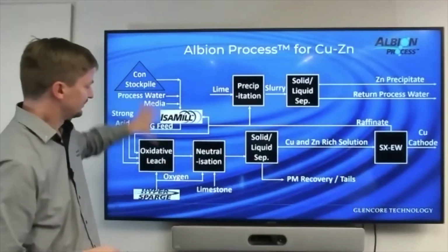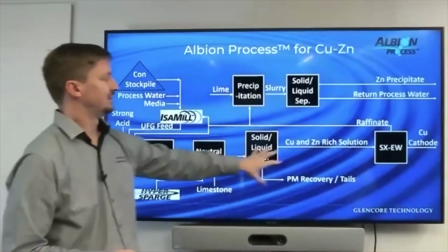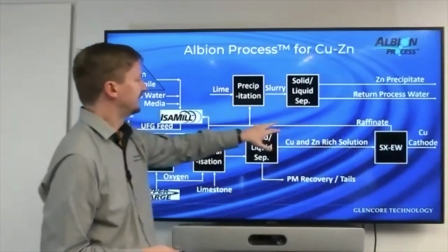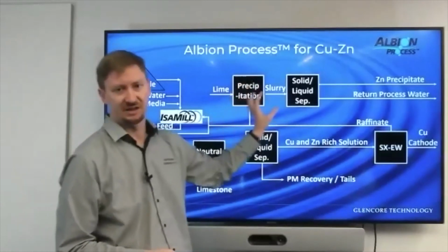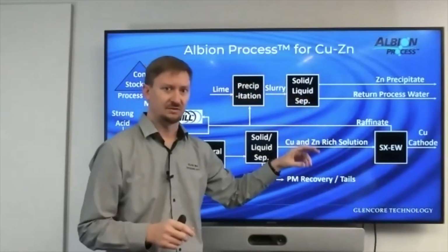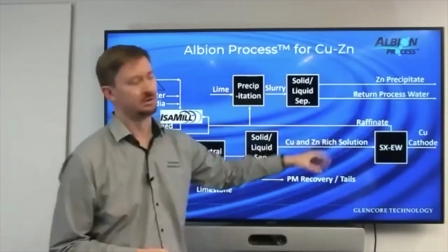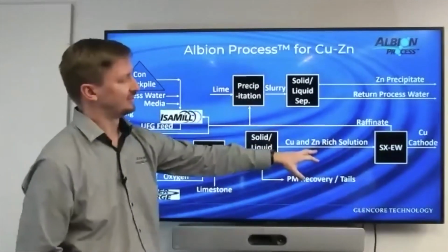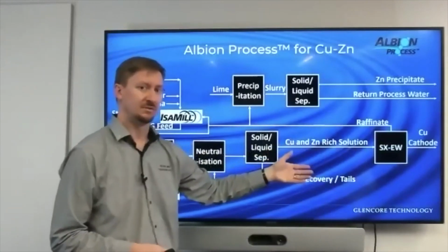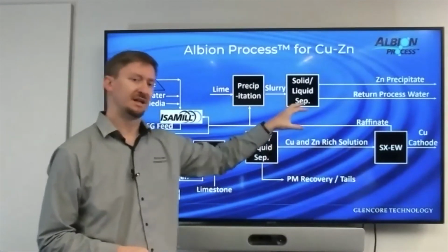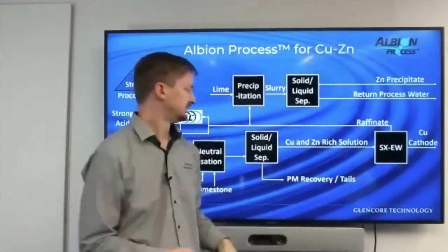So in this case, it all stays exactly the same, going to a copper cathode, you've still got your precious metal. But now, in this case, we've got a bleed stream that is getting your nuisance level of zinc as a saleable precipitate, in this case, a zinc con. So rather than being charged a penalty for having zinc in nuisance levels in your concentrate, you're now making that as a saleable product.